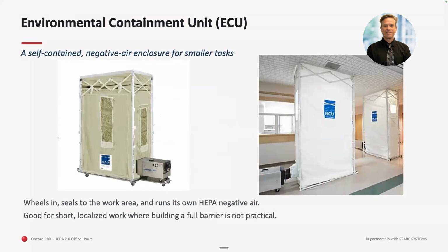I can remember in the day where we didn't have these type of things, ECU units, and what we created were some pop-up zip walls, but these things are very clever and easy to use. Most hospitals have them in place, and they'll put in their policy, if you're doing incidental work above the ceiling and you have to disrupt things, or you're in a high-risk area, you would use these ECU units, which are environmental containment units. HEPA negative air might be included depending on the risks that we put into the risk assessment that we do for ICRA, but they are appropriate containers for small spaces and effectively put up in a way that we can contain and control the dust.